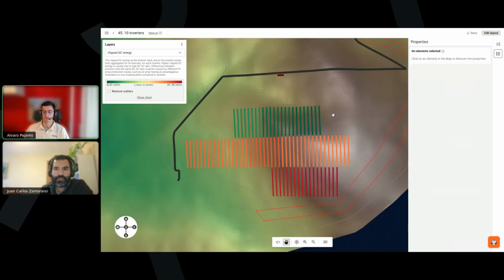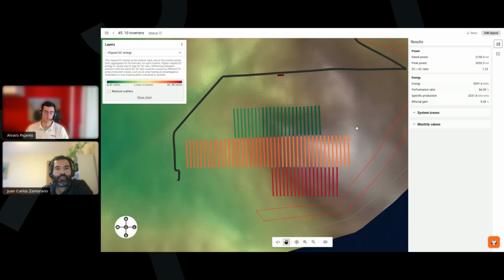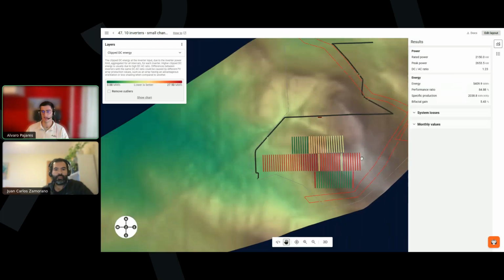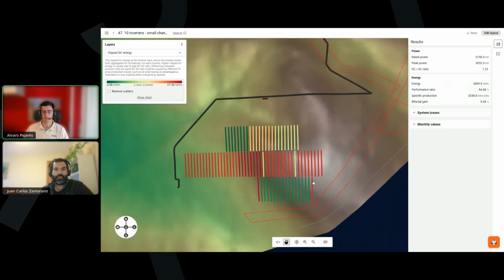And it's really interesting what we can do now with layout data and editing the low voltage groups, because even for complex or hilly terrains, we can see how this will heavily influence the energy production. So, for example, we had these 3 examples. This is the same as before, but I edited the low voltage groups a little bit, and we can see how the results are absolutely different.